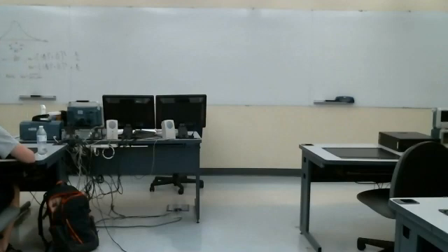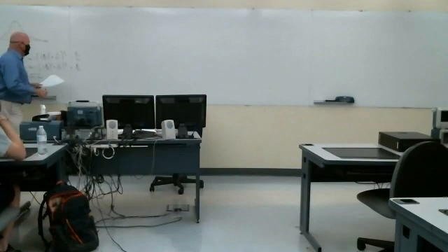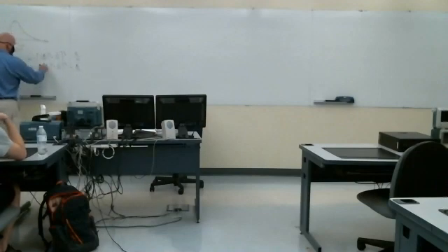The geometric mean of the cutoff frequencies is equal to the resonant frequency. It looks as if omega-0 is halfway between these. The arithmetic mean, you add them together and divide by 2, is not quite true. It's actually the geometric mean of those two cutoff frequencies. But the other formula that's really nice is the difference between these. That's the bandwidth, omega C2 minus omega C1. Fortunately, this whole square root term cancels, and the bandwidth will just be R over L.